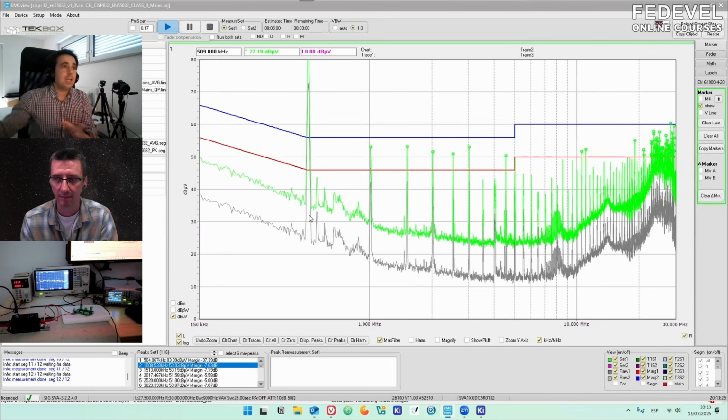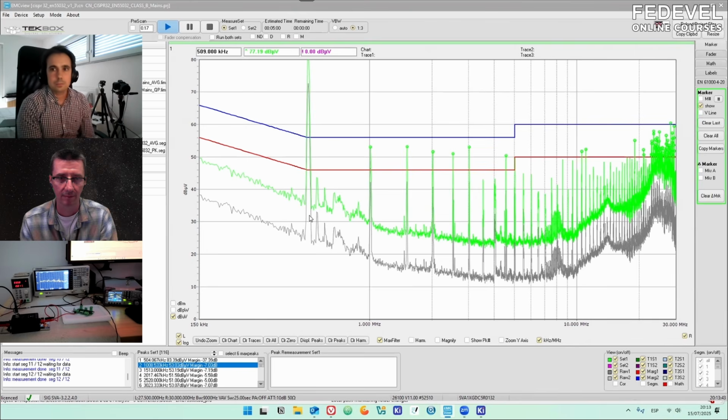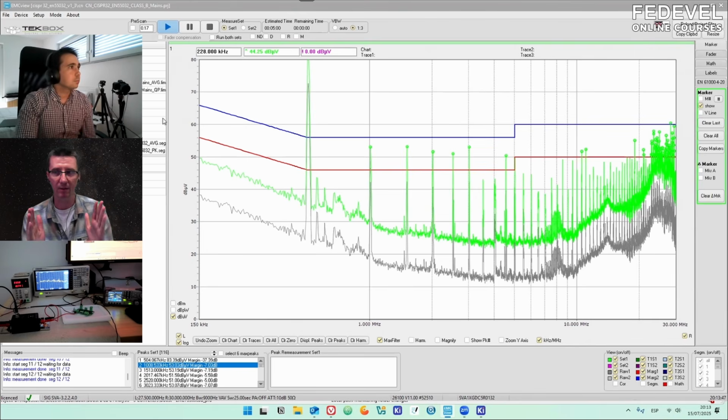And this will also be related to what we will measure in the EMC lab. So if you go from the end to the beginning, that means that with near field probes, you can already start debugging your system and identifying potential sources of problems. And I would like to point out the graph. It may look like the peaks are getting closer and closer, but it is a logarithmic scale, so that's why they are getting closer and closer. Yeah, that's a good point.